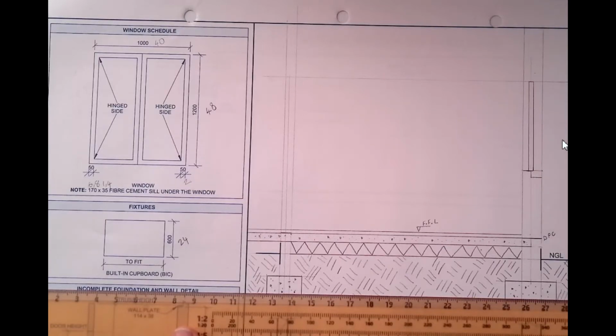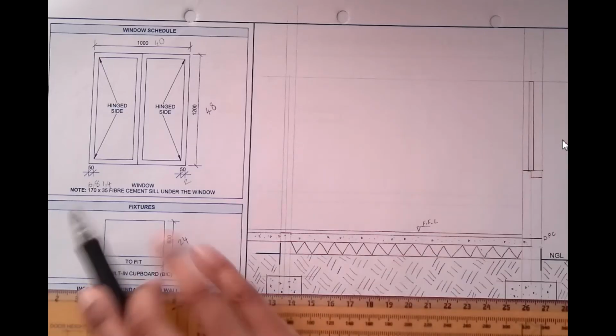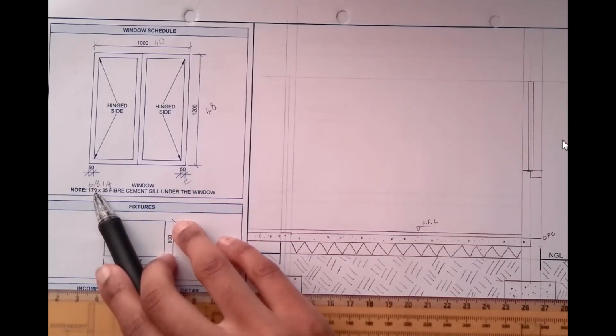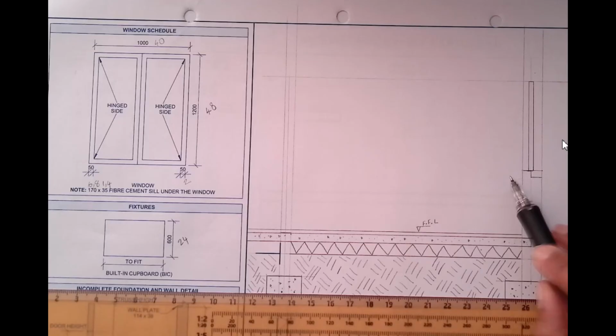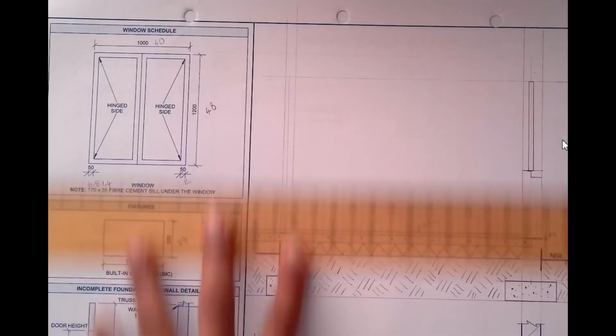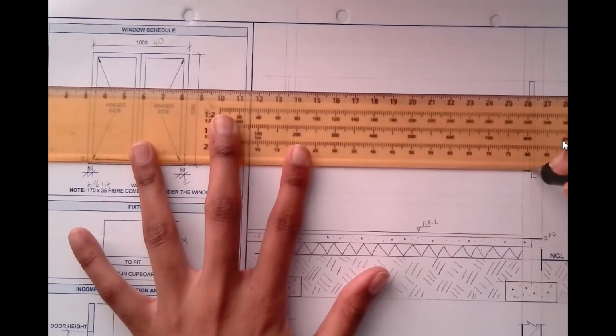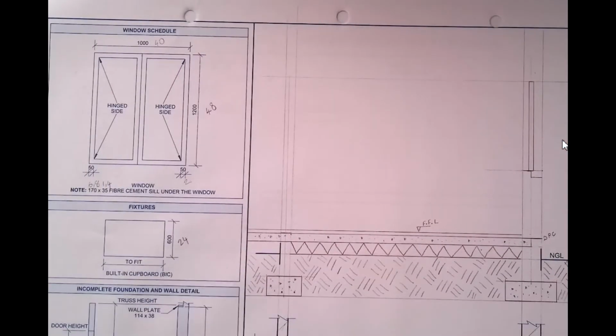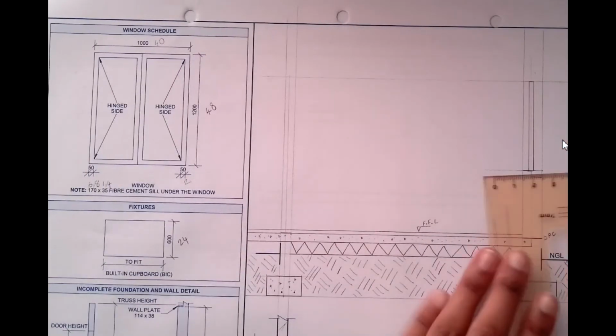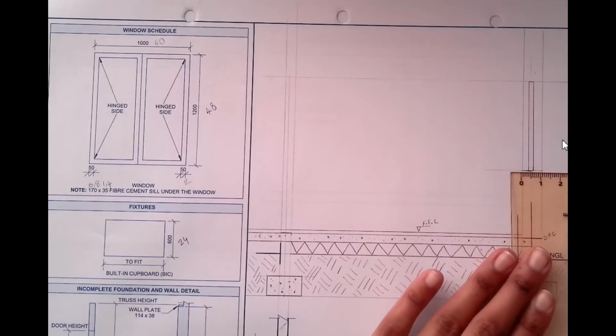So once that is done, then I'm gonna draw my windowsill. So with my windowsill, I use this corner and also that one, and then we know that my windowsill is supposed to be 6.8 long. So I'm going to start with the inside windowsill. I'm going to extend my line like that. Then I measure my 6.8.